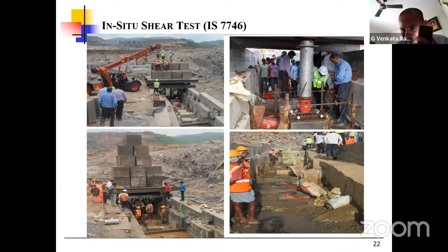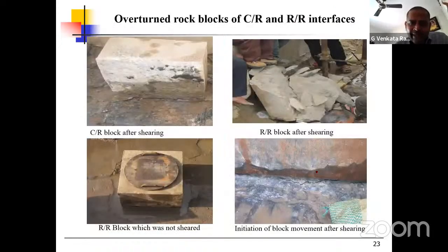I'm in the classroom. Okay, so these particular values, once we know tau 1 and W1, nothing but sigma 1, we can easily draw the Mohr circles. We can calculate those values. See, the same thing I have done, because some blocks are concrete over rock, some are rock over rock. But fortunately, the rock is so strong that one particular block we could not break, even at higher loads. But when the load is applied, see how the crack is generating here at the base.